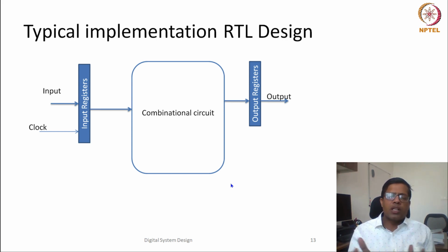Overall, the input is read from a register, and there could be a sequence of combinational design. In this combinational design, some gates give output to other gates, and so on. But overall, this whole combinational design will perform the operation within one clock period, so that the output would be available after one clock cycle. And there could be multiple such operations happening over different clock cycles.